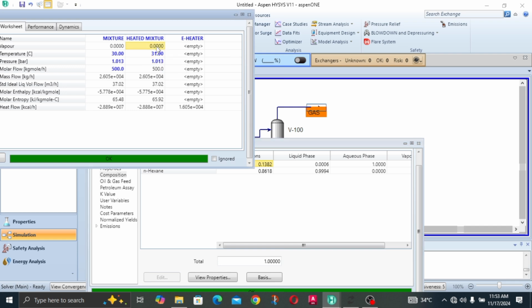But then our vapor fraction dropped to 0, which isn't a mixture. So with that, the separation cannot efficiently take place. So let's put that 40 one more time. 50. We have to make sure that our vapor fraction is anything other than 0. 60. 68.